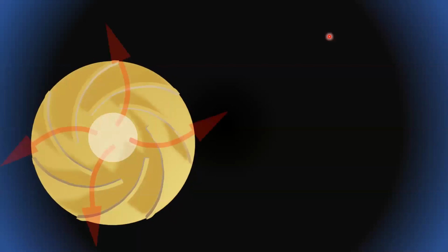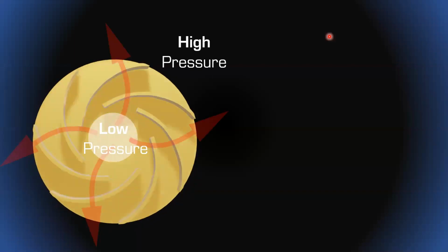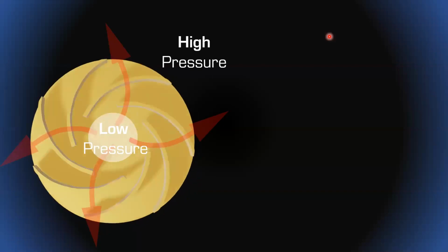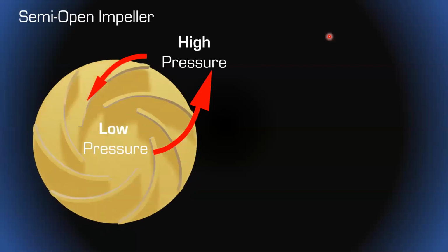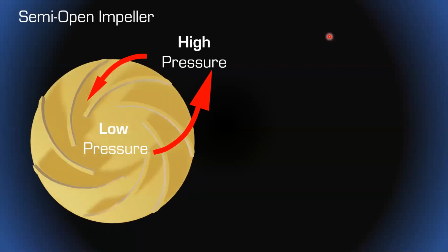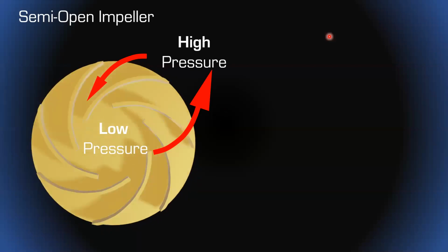So what happens while a pump is pumping? Well, it's generating this low pressure at the eye, and it's accelerating and energizing the fluid outward and developing a high pressure. Well, this could become a mixer if we're not careful. If we don't keep a close tolerance between these high pressures and low pressures, this throttling system, then we're just going to get a mixer.